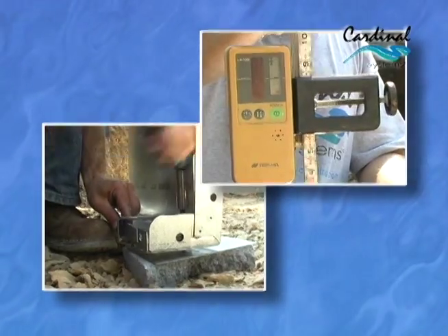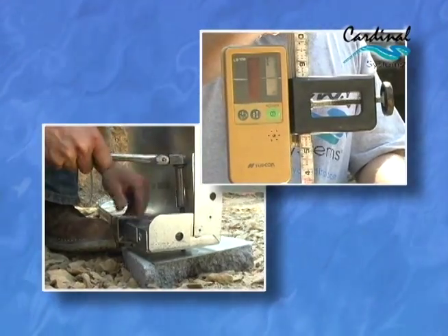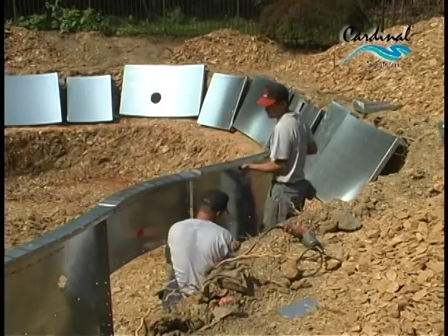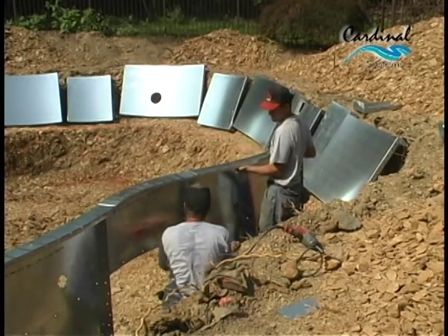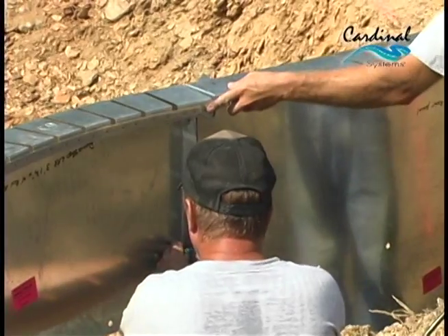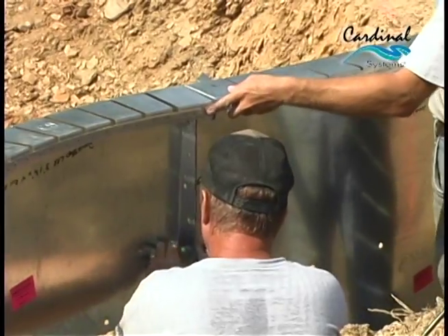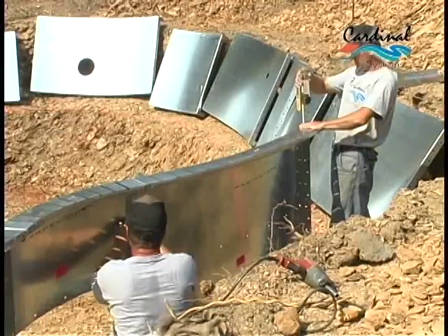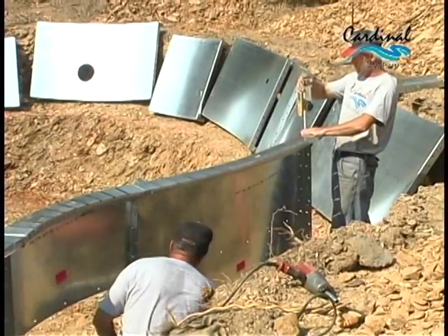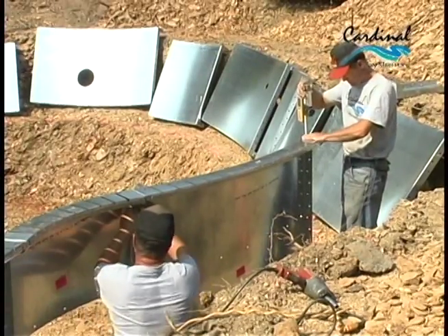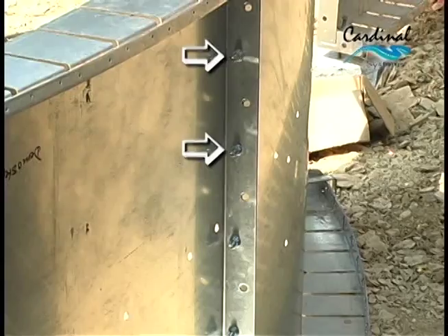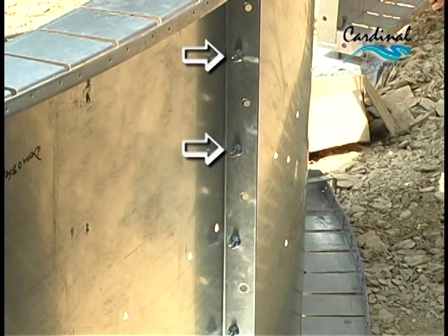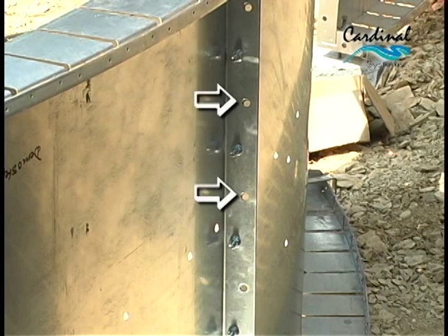Bring the panel perfectly level by adjusting the panel leveler with a wrench. With the first panel level, you can continue assembling the panels, checking for level, and using the panel leveling system as you proceed. Remember, use the inner holes to connect panels. The outer holes are reserved for plastic step units and ladder panels.